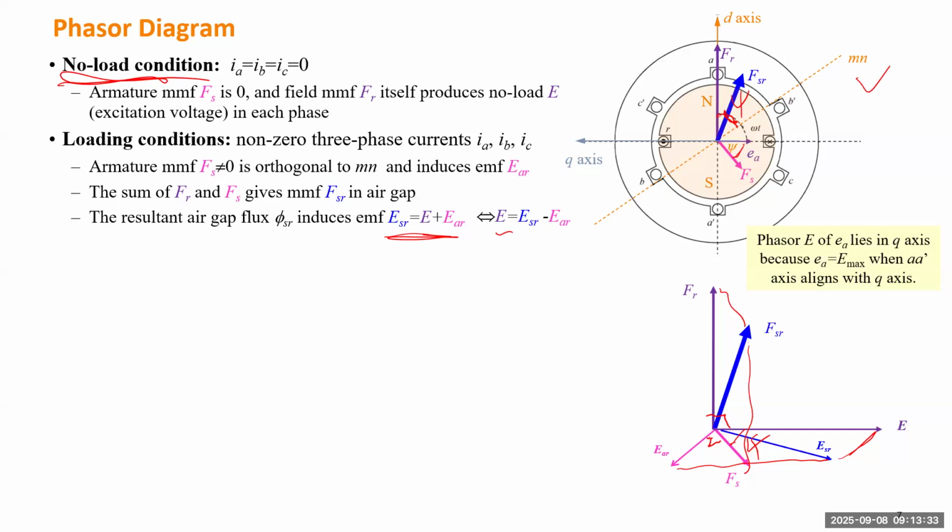If you're familiar with batteries, if it's not an ideal battery, the battery will have an internal voltage, could be 1.5 volts, 2 volts, 3 volts. But when you connect the battery to an external load, depending on the resistance built up inside the battery, the voltage you can measure at the terminal in the circuit can be lower, usually slightly lower. Okay, so this E will be the internal electromotive force. So this one will be constant. That one only depends on the field current.